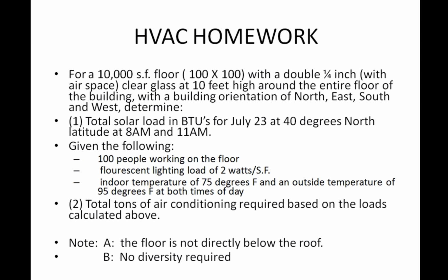The factors are, there's 100 people working on that floor. You're using fluorescent lighting loads of about 2 watts per square foot for that entire floor. And there's a 20-degree difference between the temperature you're maintaining on the inside, which is 75 degrees, and 95 degrees outside. Just to make things simpler, we're going to use that 20-degree difference both at 8 a.m. and 11 a.m. Okay? So that's what you have to give me. Don't take into any consideration for diversity. Just give me the full answer at 100%.